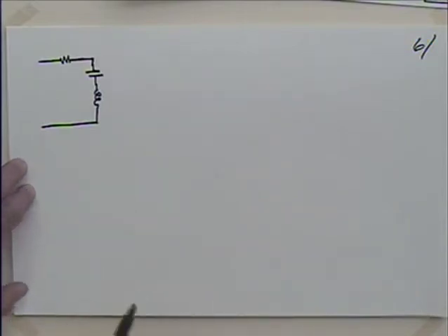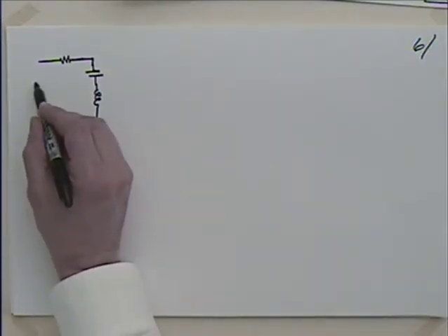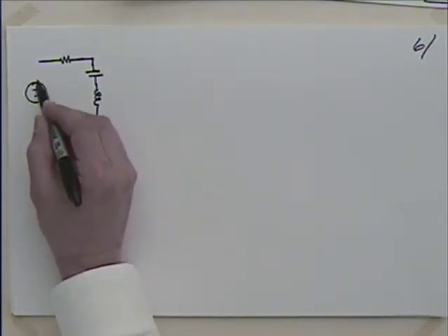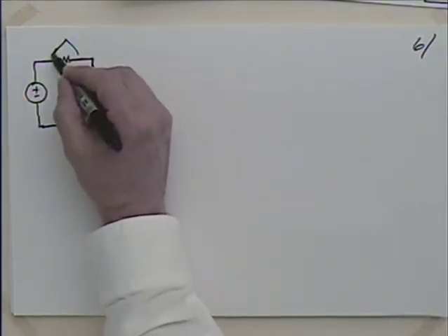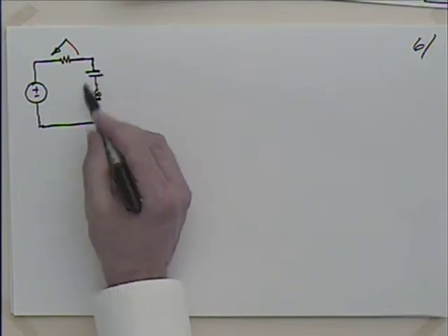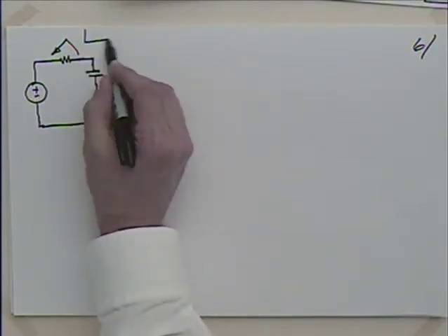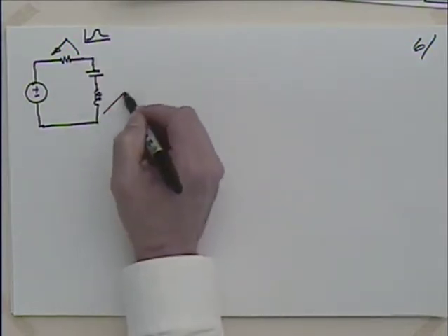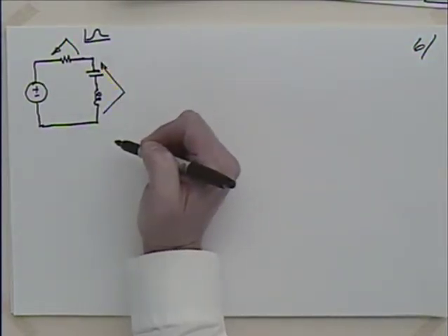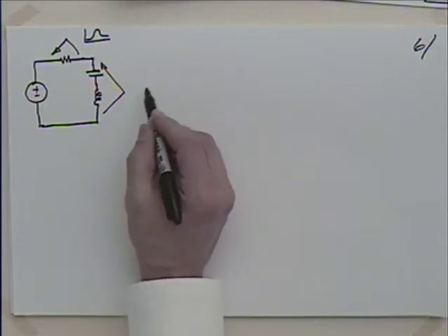And whether you want a band pass filter or a band reject filter depends on where you're tapping the filter, so to speak. I mean, if we take the voltage across here, as this goes to resonance, this part goes to 0, right? And that's going to give me a band pass, isn't it? If, however, I look at the voltage across here, some of you will recognize this from yesterday in laboratory, that goes to 0 and we get what?